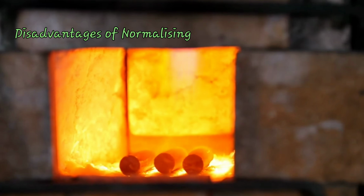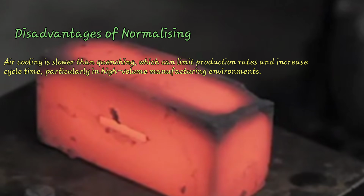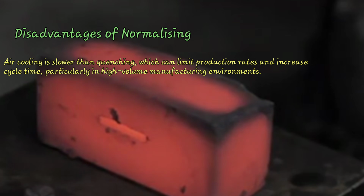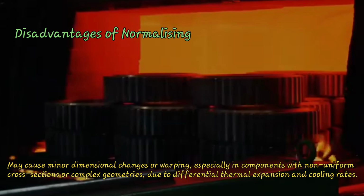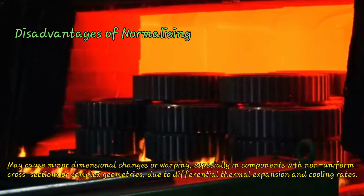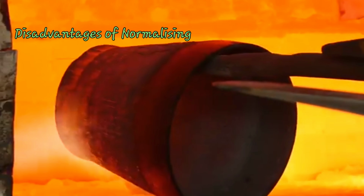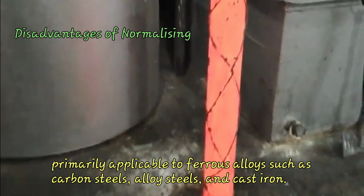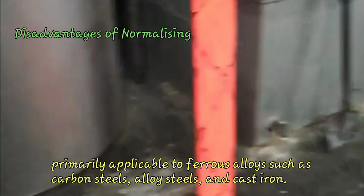Disadvantages of normalizing. 1. Air cooling is slower than quenching, which can limit production rates and increase cycle time, particularly in high-volume manufacturing environments. 2. May cause minor dimensional changes or warping, especially in components with non-uniform cross-sections or complex geometries, due to differential thermal expansion and cooling rates. 3. Primarily applicable to ferrous alloys such as carbon steels, alloy steels, and cast iron.